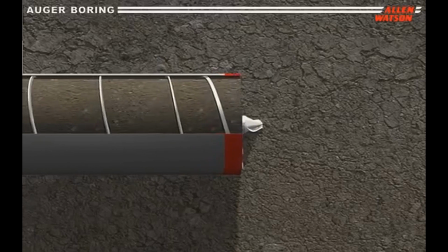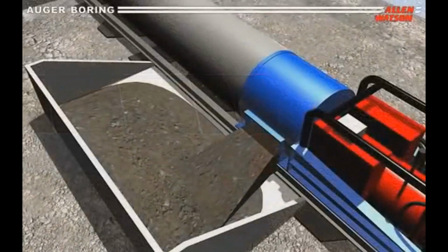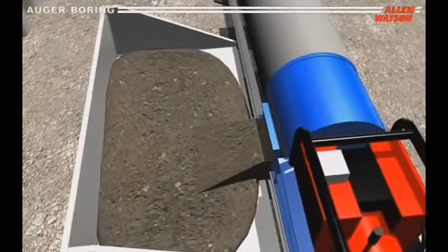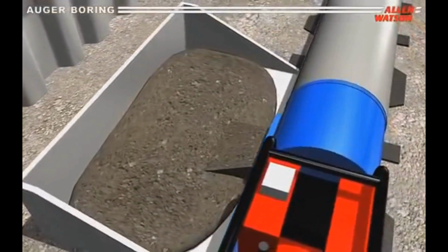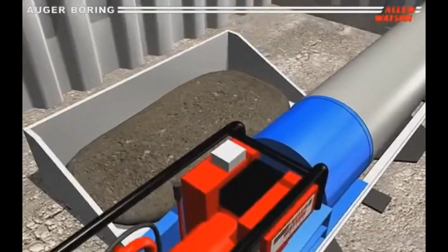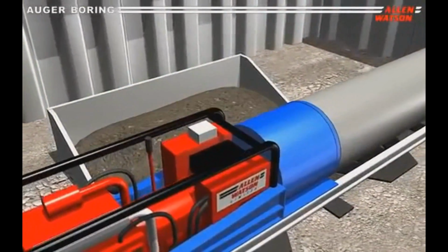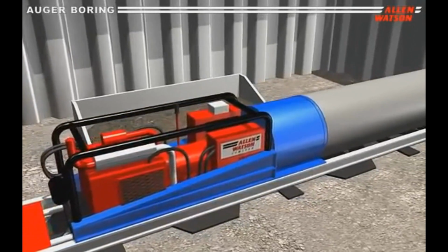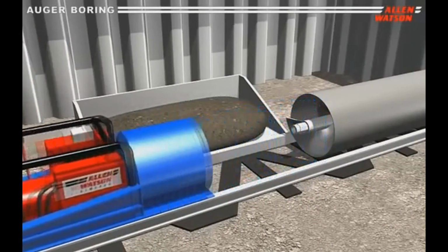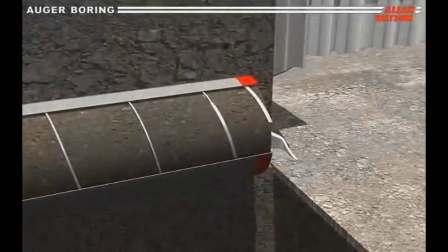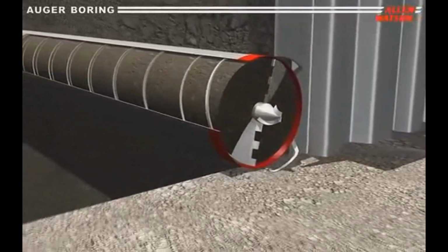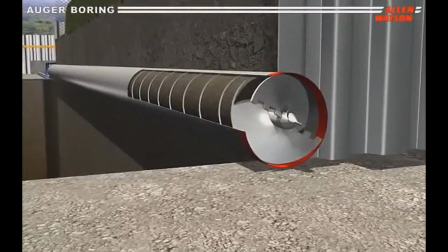Depth of boring. Borings should extend below the depth where the stress increase from the foundation load is significant. This value is often taken as 10% of the contact stress. For the square footing, the vertical pressure profile shows this depth to be around 2b. Since footing sizes are seldom known in advance of the borings, a general rule of thumb is 2 times the least lateral plan dimension of the building, or 10 meters below the lowest building elevation.